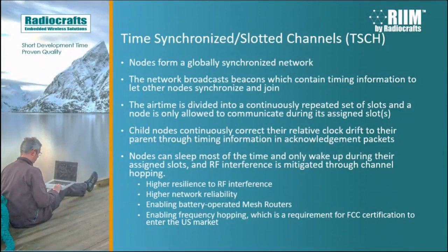The network broadcasts beacons, which contain timing information to let other nodes synchronize and join. The airtime is divided into a continuously repeated set of slots, and a node is only allowed to communicate during its assigned slot. Child nodes have to always correct their clock drift to their parent through timing information in acknowledgement packets.